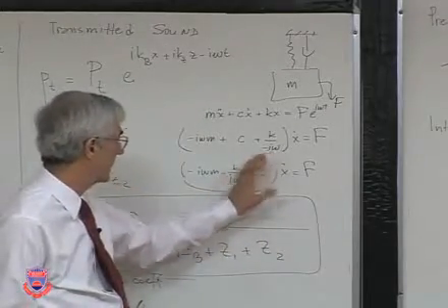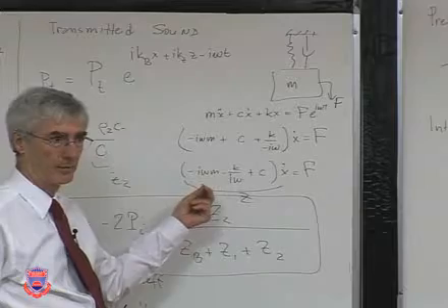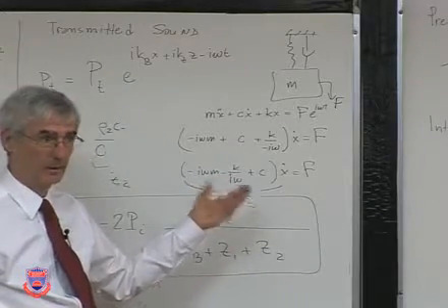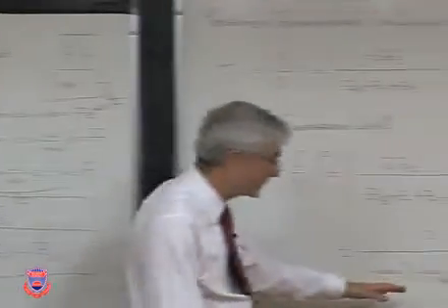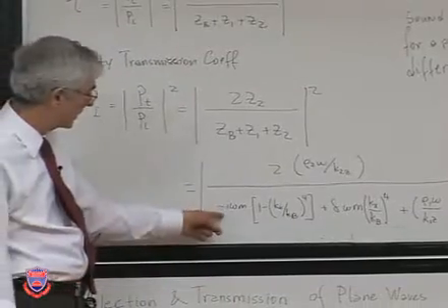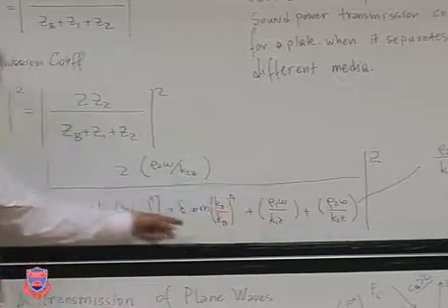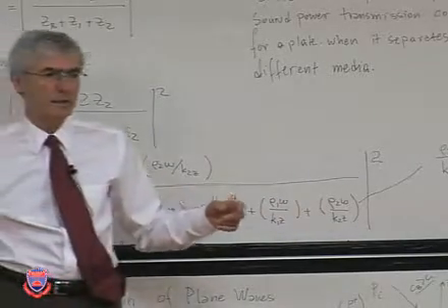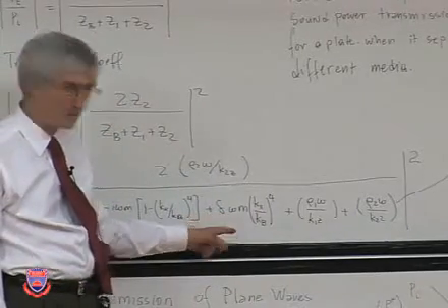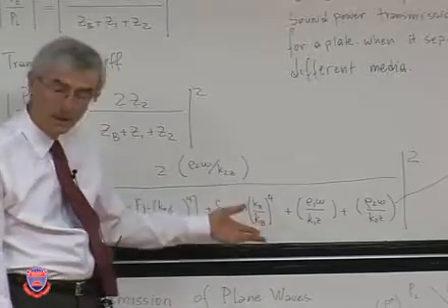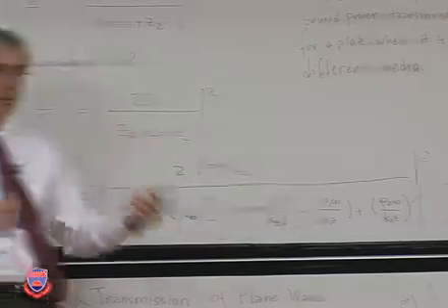Okay? If you don't have that, you only have the reactive part. And what does the reactive part correspond to? If it's zero, we call it the resonant condition. Okay? Stiffness and inertia. So when you look at equations like this, when there's an impedance, you look at the imaginary part, the reactive part, and you look at the real part. Real part, we said energy is dissipated. How is the energy dissipated here? Exactly. Okay? Delta here describes the material damping of the plate.